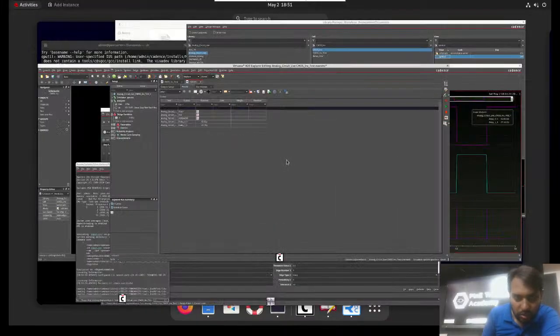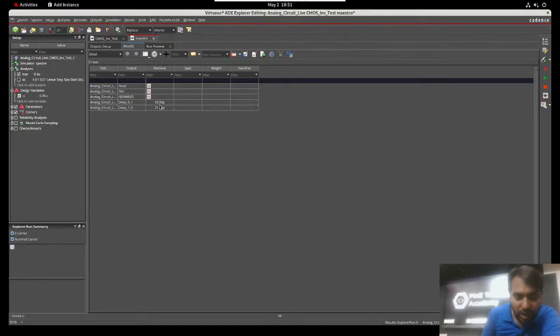Okay, so you can check it. This is 92 picosecond and 27 picosecond. That delay for 0 to 1 is higher. When input is rising, 0 to 1 it is taking 92 picosecond, but 1 to 0 it is taking less delay, that is 27. So there is a difference. Why? Because that W by L is not perfectly matched. If it is perfectly matched at 500 millivolt, or you can provide it in such a way, you can reduce the delay also.